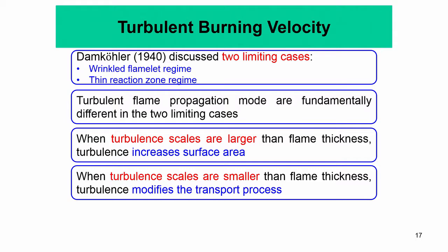But you see that in a laminar flame both the molecular diffusion processes as well as reaction are very important. If you remember, your flame speed was essentially the geometric mean of the reaction rate and the thermal diffusivity, right. So, now if you have very strong turbulent diffusivity which overrides your thermal or molecular diffusivity, then this turbulent diffusivity can become an equally important or even more important parameter than the molecular diffusivity in the global propagation behavior of turbulent flames.